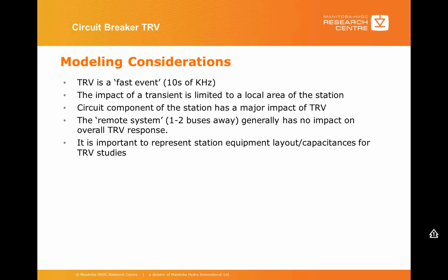The remote system, say one or two buses away, generally has no impact on the overall TRV response, but it is a good idea to develop at least one bus away system, which provides the correct fault levels on the substation being studied for the TRV study.